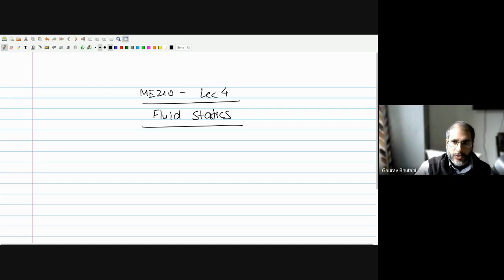in fluid mechanics, we need to identify certain variables so that we can completely characterize the flow. So we talked about these fields called the velocity field and the pressure field. If you know about the velocity and the pressure fields, then you have characterized the flow completely. Of course, fluid properties and so on are known, but in terms of the flow behavior, this is what you need. Temperature is required if you're interested in energy balance.